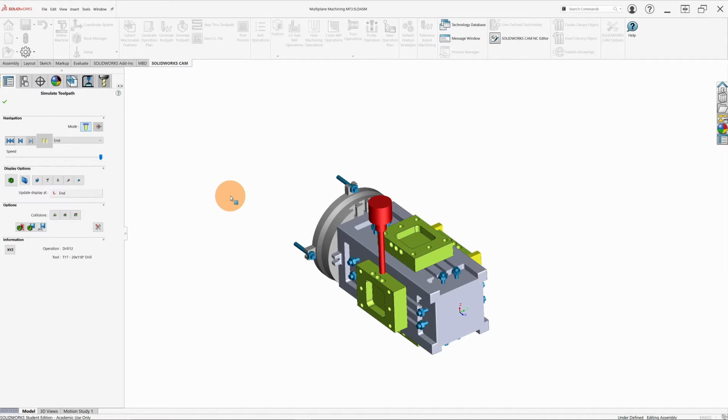What I am going to take a look at now is how to improve the efficiency of the machining operation. If we're to observe the machining here, we're rough milling, and then we have a tool change where we're center drilling the top. Then we change the tool for the 16mm drill bit. We're drilling the 6 holes. Then we change again to the center drill and drill the part here which is on the right hand side. We change for the 20mm drill. We drill it. Then we change back to the center drill and center drill the part here on the left and back to the drill. So there's a lot of duplication.